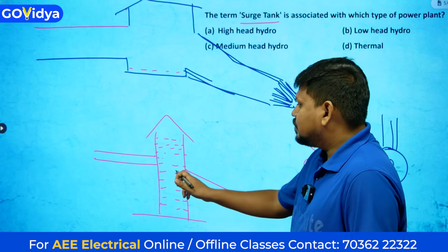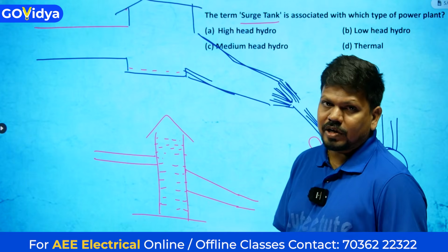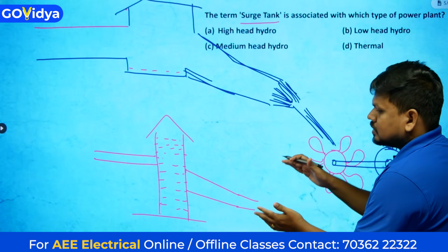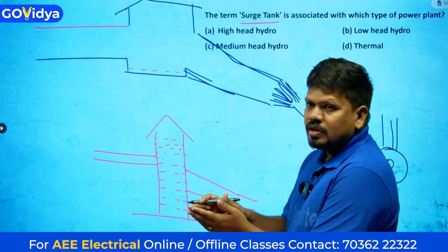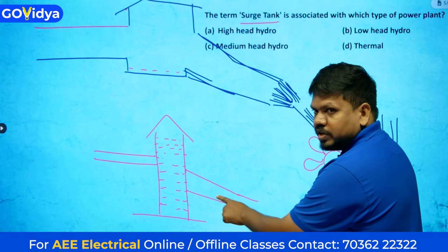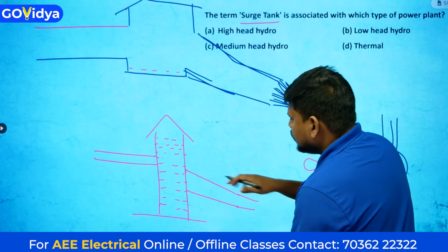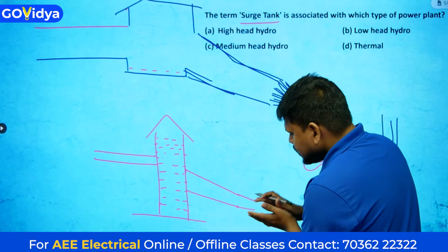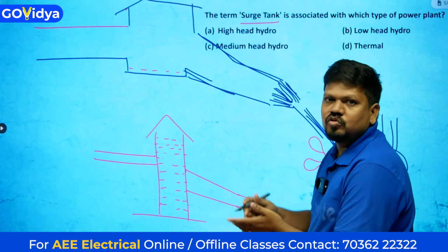And this gives safety to the penstock, because whenever the nozzle opening is increasing and decreasing like this, pressure will build up, positive and negative pressure. If it is opening, positive pressure will build. If it is closing, water wants to hit back, so negative pressure will come.